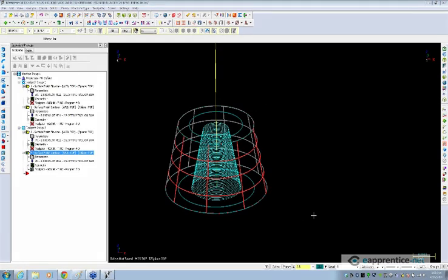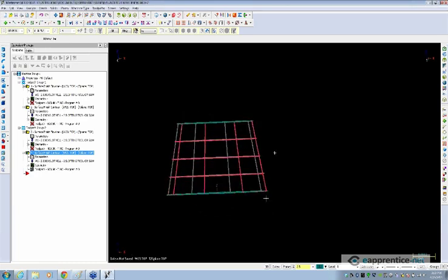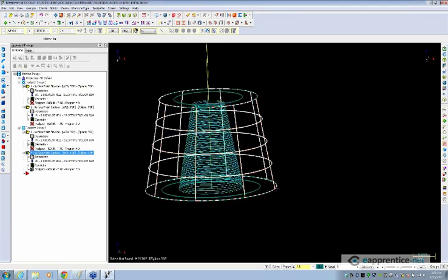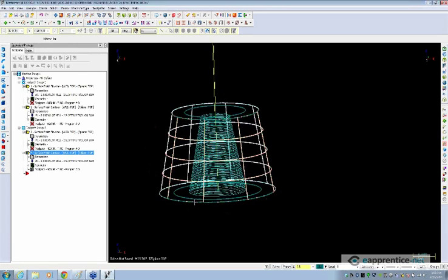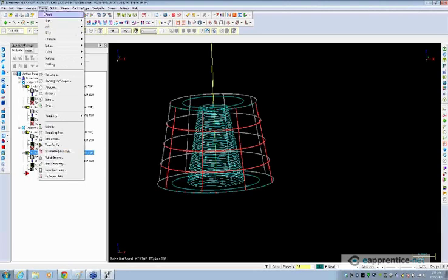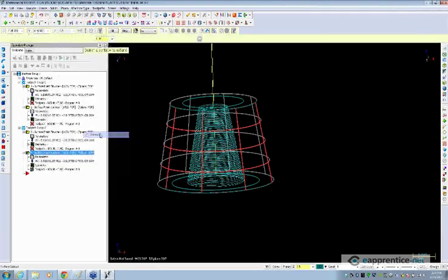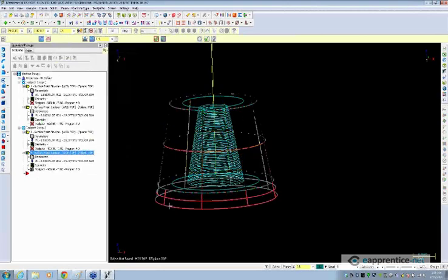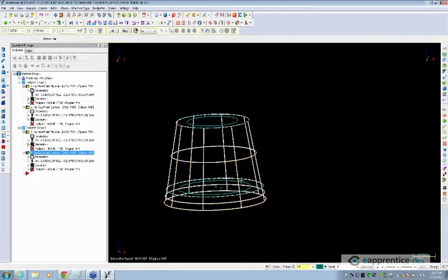So let's see. We have a question coming in from Dwayne. Can you extend the bottom of the surface cutting without creating extra surfaces? Yes. In order for you to extend that surface, though, it has to be untrimmed. So if it's a trimmed surface, you must first untrim the surface before you're allowed to extend it. I can do it now because it's already an untrimmed surface. Create surface, extend, half-inch extension there. I'll click on it and extend it, and it makes one single surface.